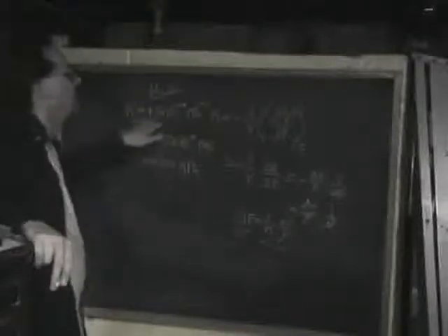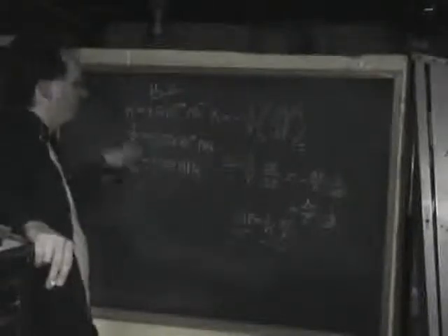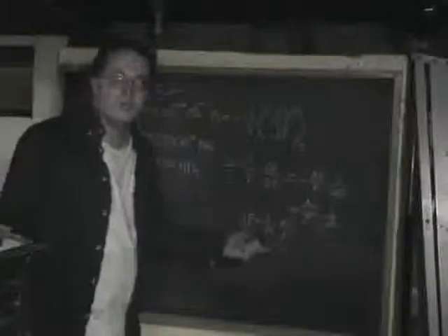number. What it reflects is that water isn't very compressible compared to something like air. That's why the isothermal compressibility of water at 4.5 times 10 to the negative 4th is relatively low. Its inverse, therefore, is quite large. It takes a big change in pressure to affect a relatively small change in density.